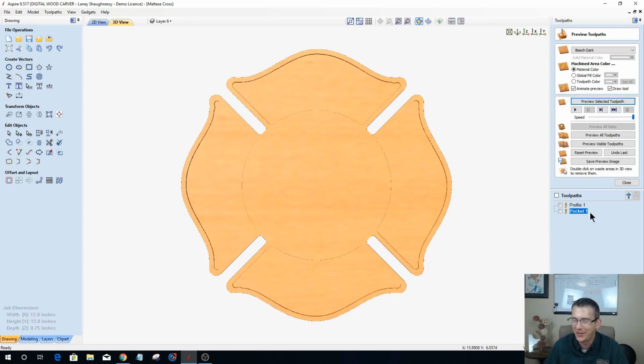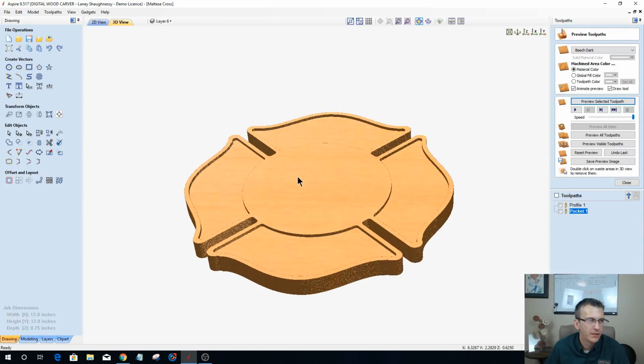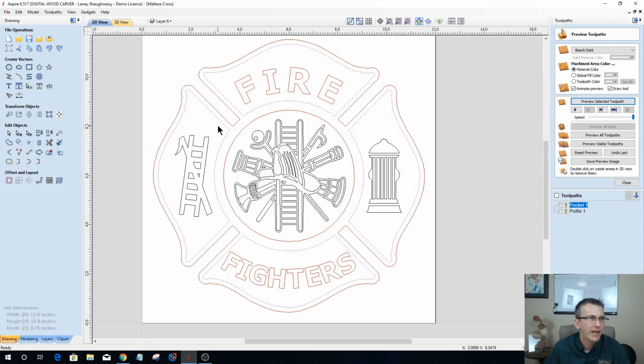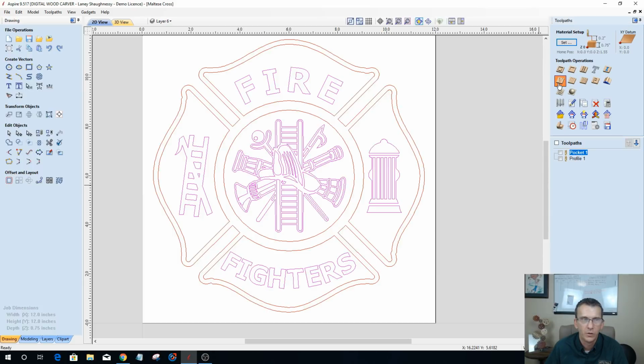I appreciate that. Kudos. All right, so you can see where we're heading here on our shape. Let's put our pocket toolpath at the top of the list. If I come in here and now I wanted to V-carve this stuff, I could select everything, turn off the outside shapes. All I want is my objects selected, and I could go in and do a V-carve toolpath.